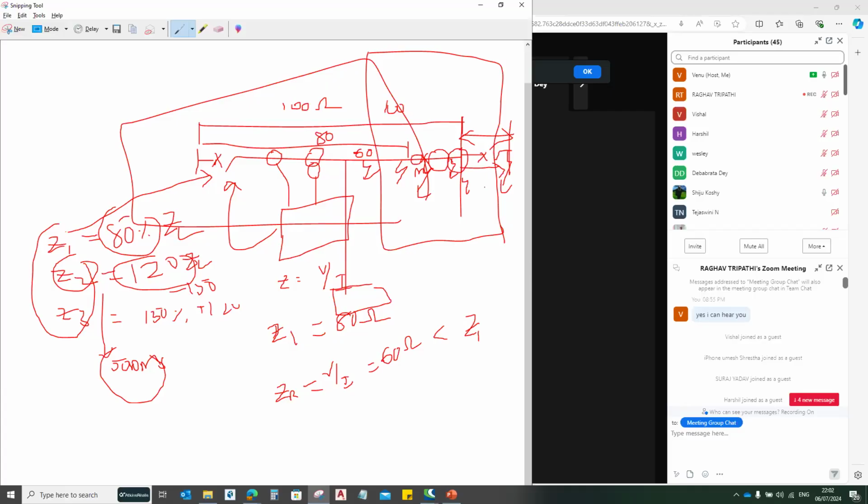I don't need to trip this circuit breaker, so that I can deliver continuous power supply to this user by tripping only the other circuit breaker in case of a busbar fault.